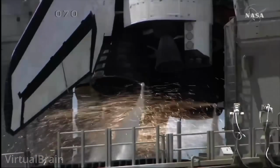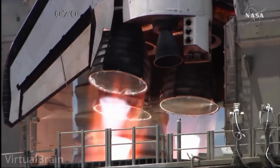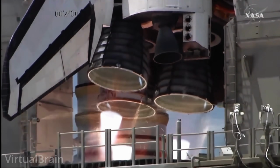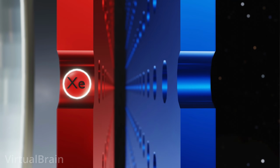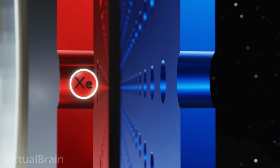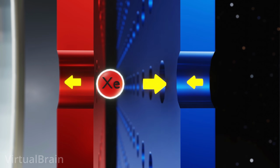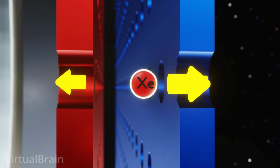To give you a point of reference, the speed at which the gases are ejected in a rocket is only about 3 kilometers per second. Returning now to Newton's third law that I mentioned at the beginning of the video, the principle of action and reaction, we will know that the forward thrust will be equal to the force applied on the xenon ions to accelerate them to those velocities.